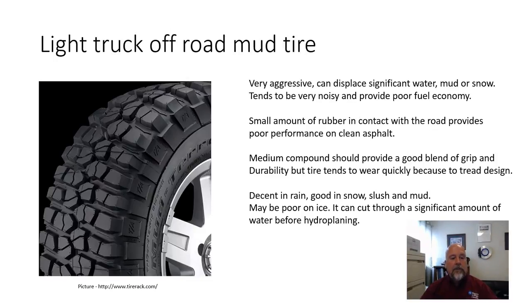Okay, light truck, off-road, and mud tire. Here, the way the tread blocks are arranged, you get more across the tire, so you can get more linear acceleration, so you can accelerate and brake better in very loose ground. These tend to wear funky, make a ton of noise, but they work even better off-road. So again, you've moved your compromise now from fuel economy and durability and roadworthiness to better performance off-road.